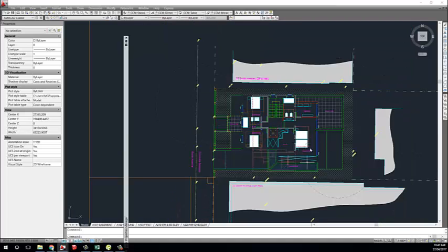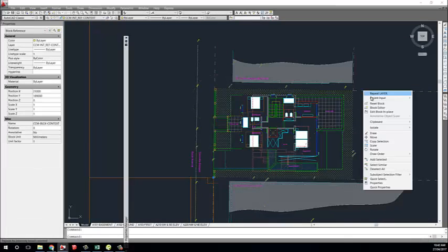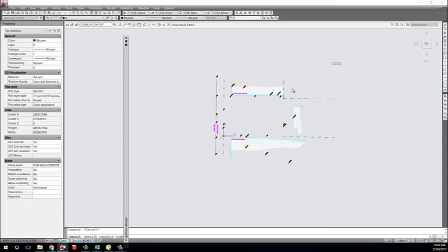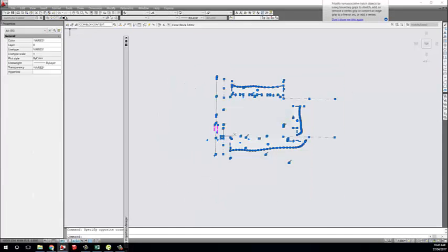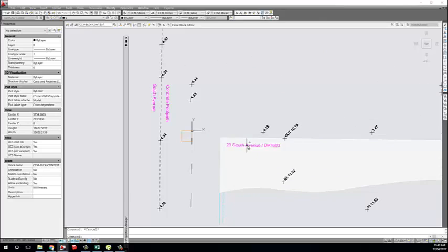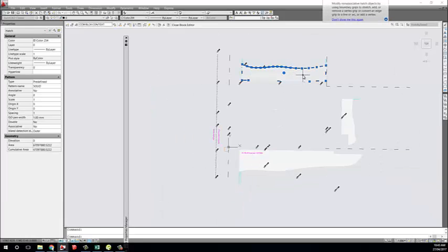Once you get used to the drawing, you understand the philosophy behind, so you could perfectly draw everything in layer 0. In fact, in the block editor, I probably think that just drawn everything in layer 0. Yeah, you see everything in layer 0. Just considering how things are going to be printed, but this is magenta. Normally annotation is in magenta. This is for the cavities and the fill. We normally use 254 hatch solid.